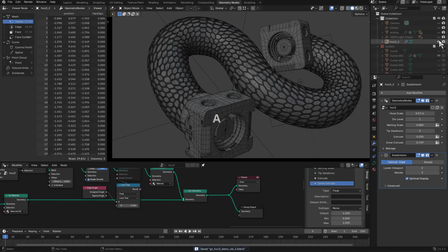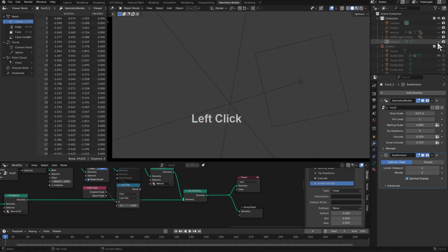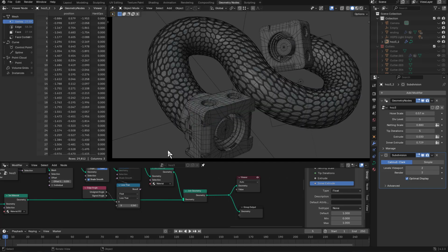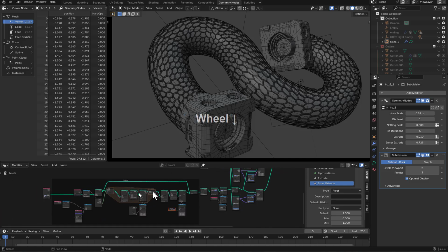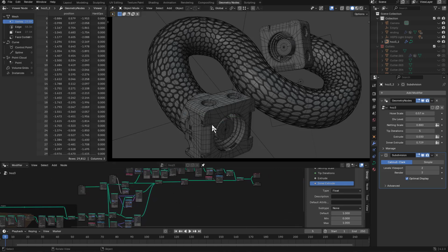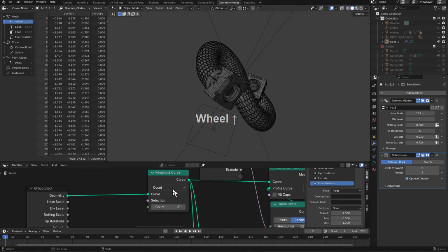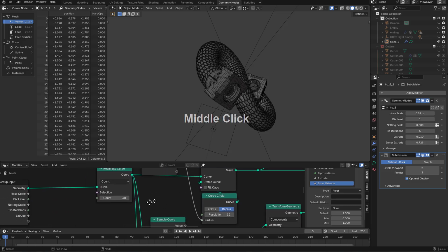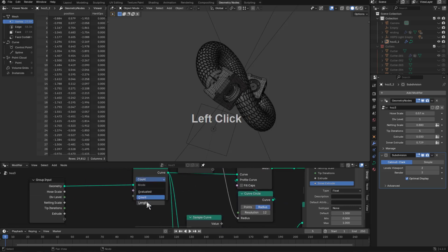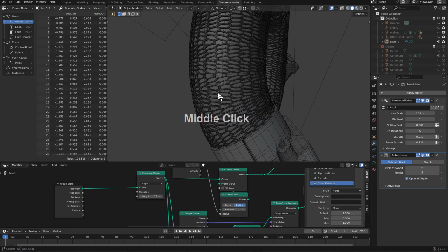So now we see that we can solve this into quads, still separate areas off into vertex groups, use it to go inside of geometry nodes for us to perform operations to, in addition to all the stuff that we did when it came to making this into a hose. Another thing too that we could do while we're here is changing resample curve, that instead of it being on count, we could have it work on length, which will probably give us something regrettable because that's probably not the correct one, but it is.